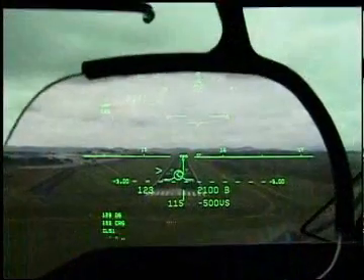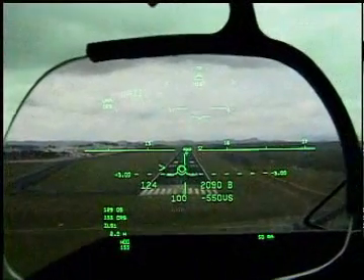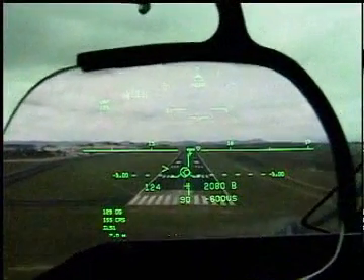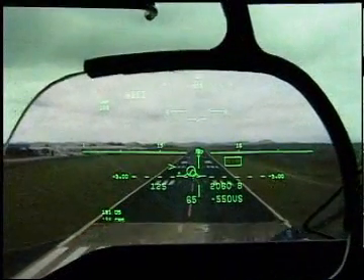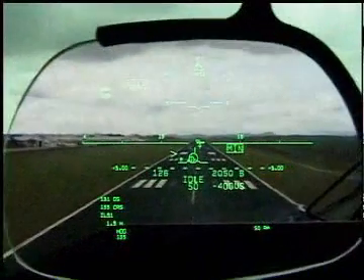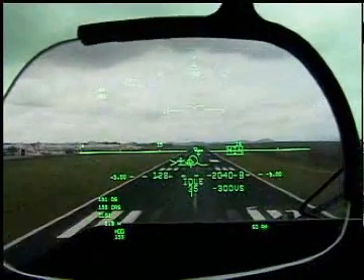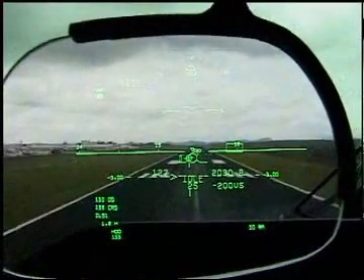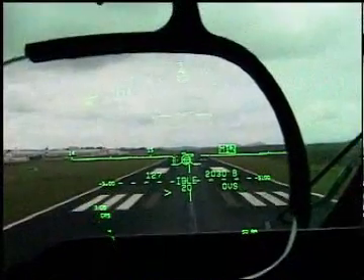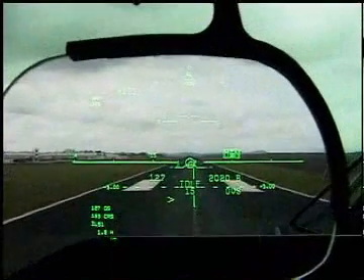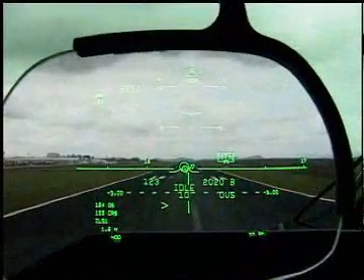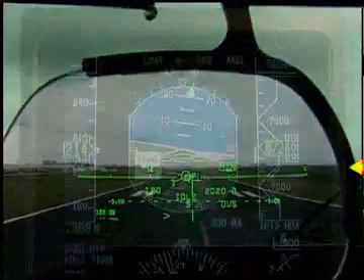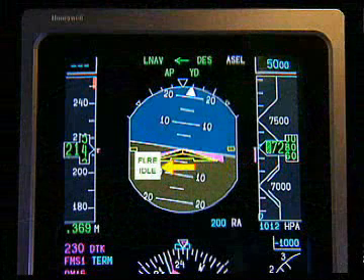The flare maneuver is designed to transition the aircraft from the approach attitude to the touchdown attitude while maintaining positioning and performance requirements to meet touchdown criteria for Cat 3A landings. This includes continuing to track the runway localizer and establishing an acceptable touchdown sink rate while refraining from long landings. In order to reduce the longitudinal touchdown distance, an idle command is displayed on the combiner and the first officer's PFD, alerting the crew to reduce thrust to idle.